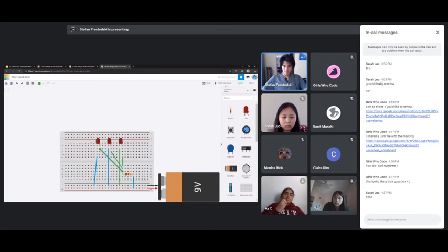Okay, it's around. See all three light up. And if I remove the light bulb, the other two aren't affected. So this is one advantage of a parallel circuit. If say one of these lights goes dead, the other two aren't going to be affected, whereas they would be if they were all in series. This is why you often see lighting strips. Most lighting strips are done in parallel rather than in series, so that if, let's say, one light fails, the entire strip doesn't go dead.